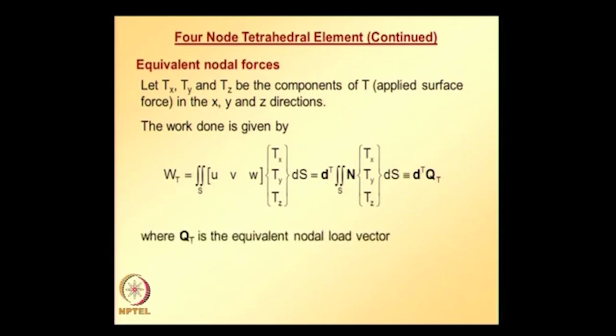where q is the equivalent nodal load vector defined as surface integral of the matrix consisting of finite element shape functions times the components of tractions.